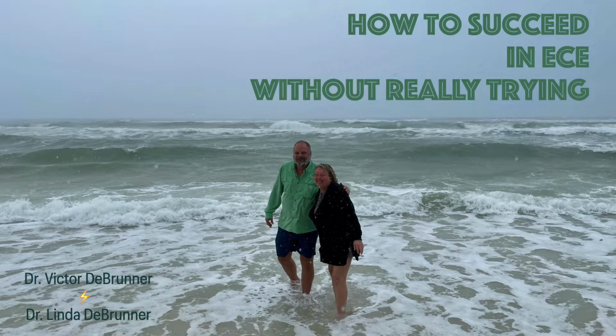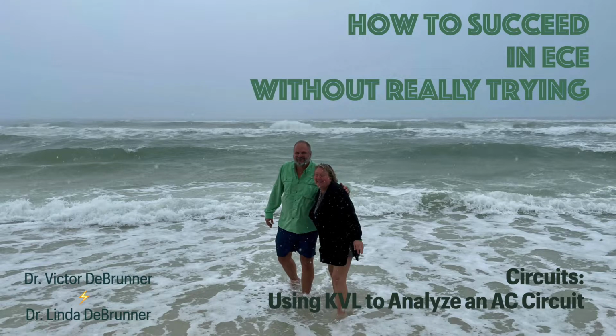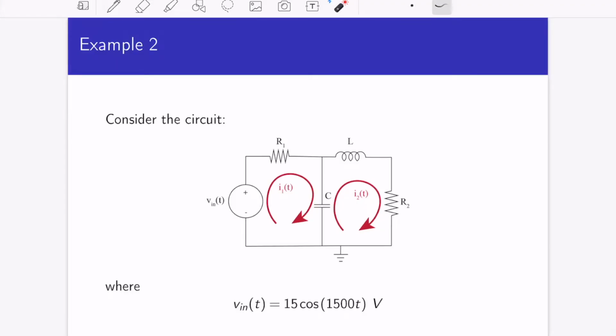I'm Dr. Linda DeBrunner, and in this video, I'm going to go through an example to analyze an AC circuit using mesh analysis. Okay, let's consider another example. Here's a circuit with two loops. This time we're going to use KVL. Suppose I give you the input is going to be 15 cosine of 1500 t volts.